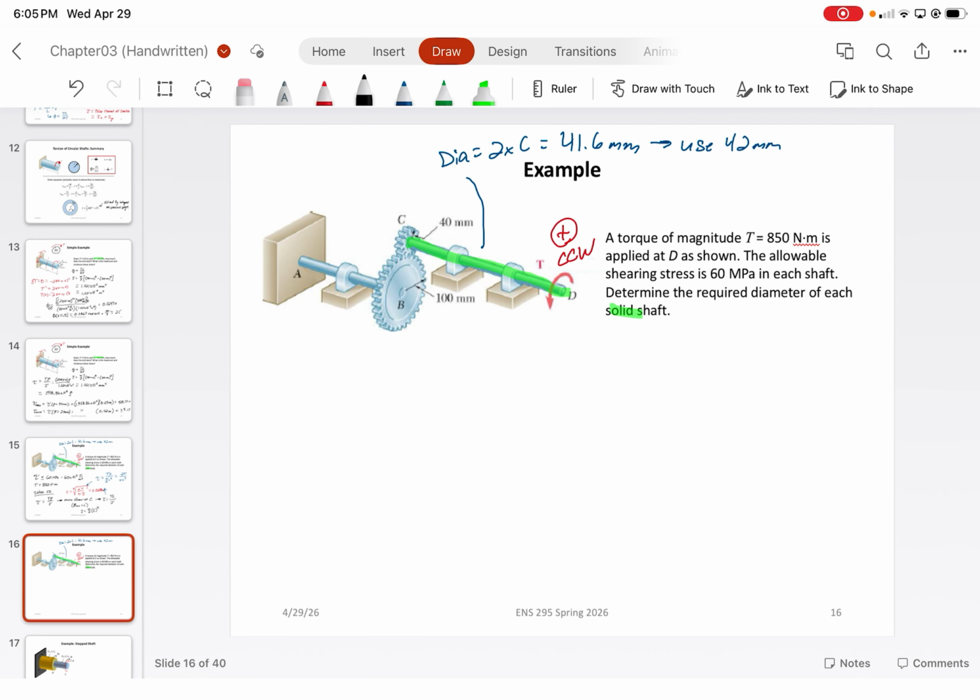Yeah, because you're multiplying it by the big 100, and then you're dividing out that 40. Yeah. All right. So basically, the torque in rod AB is exactly what he said. It would just be whatever the torque in rod CD is, and then you would just multiply it by the ratio of 100 millimeters over 40 millimeters. That just comes from gear ratios.